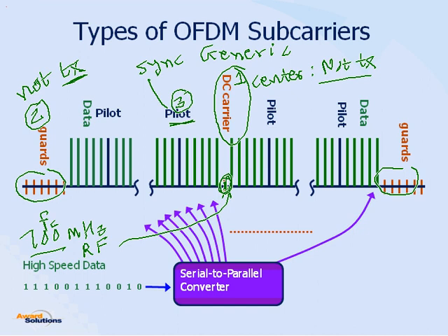So same idea here. We will use the help of the pilot channel for synchronization. There are some other signals also, but one of the functions of the pilot is synchronization. Another function is that it acts as a reference signal. When we are trying to get our data, we will use the pilot channel as a reference signal, and that will help us correct some errors on the data channel.